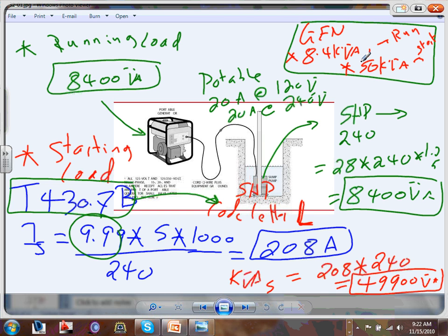volt-amps. I got a question. On the chart where you're taking off the L, the code letter, you go to the highest number, because it's 9 to 9.99? That's the worst case scenario, unless you know otherwise. Unless the manufacturer's document says no, go to the lower. Your worst scenario would be the 9.99.